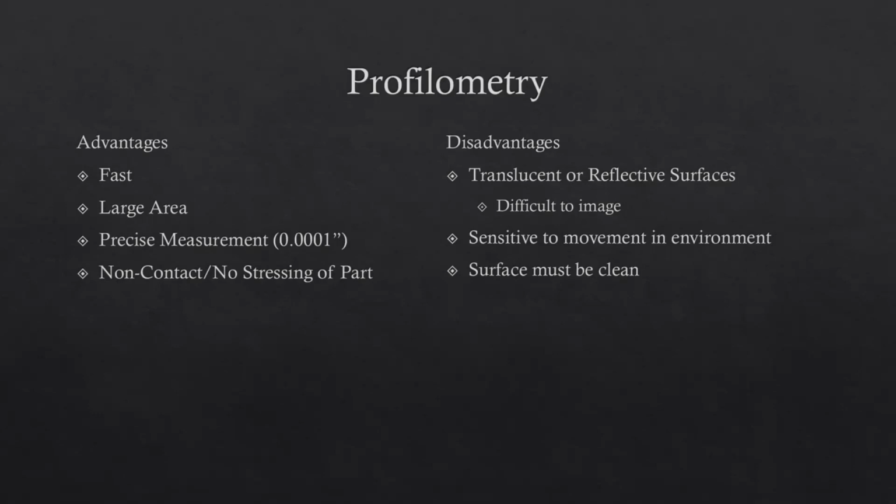We were trying to do this in a hangar, and it didn't take much. Somebody walking up the steps of the airplane would throw it off. I mean, we're talking about thousandth to 10,000th of an inch measurements using a camera. So if someone starts to walk up the steps and the plane shifts just a little bit in relation to the camera, it's done. You have to start over because you have to reset your reference plane.